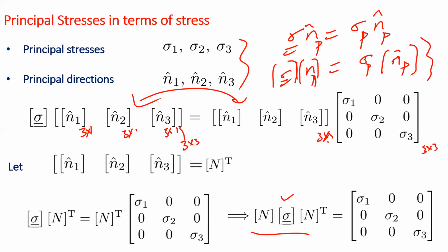I'm writing the stress, given a stress tensor. Even if you know the principal stresses, we would perhaps be in a position to identify the values of N. Or if you know the principal normals, without even solving the eigenvalue problem, one can identify the values of the principal stresses. So the analysis done on this particular slide is not something new to you. I've just recast whatever we know.